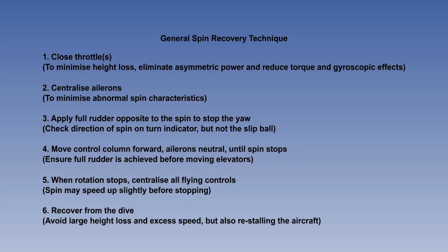Recover from the ensuing dive with back pressure that increases progressively with speed, remembering that too slow a pull-out could result in excess height loss or exceeding aircraft speed limitations, or both, and too abrupt a recovery could result in a further stall at a higher speed. Reset the power as necessary to resume normal flight, taking care to stay in limits.